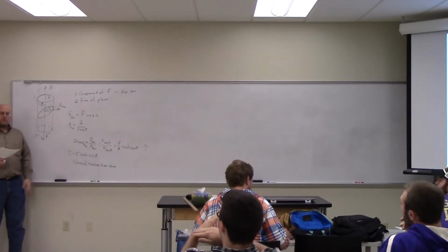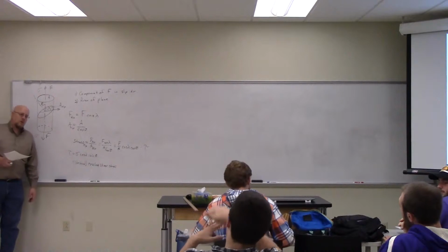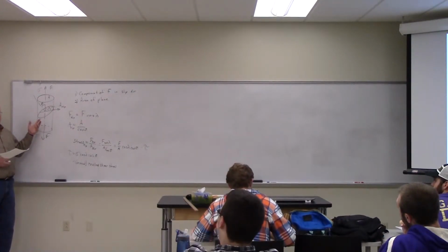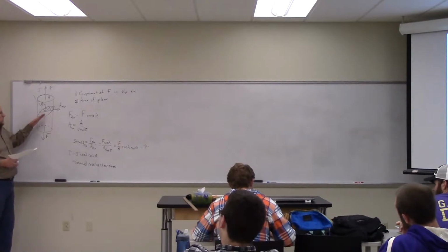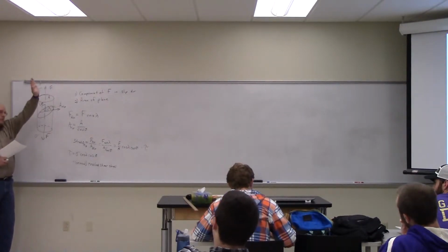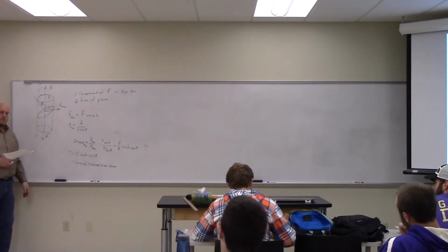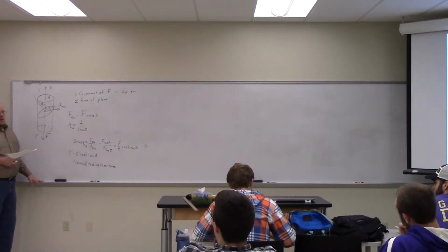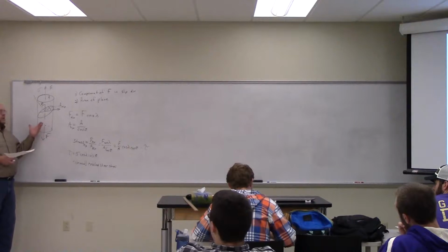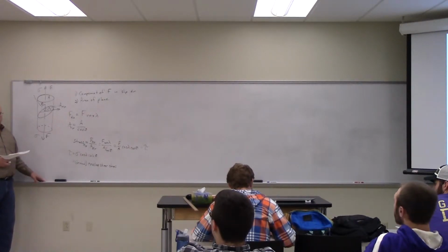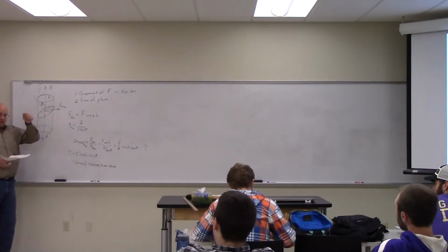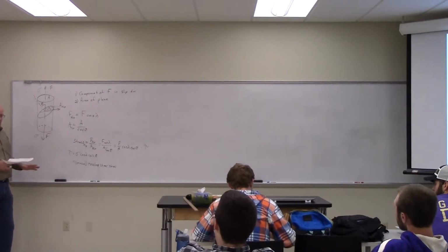So when that breaks, they're going to be like just a slope? So if this were a single crystal, like this, I pulled a single crystal like this, and it yielded, indeed, they would shear past each other, and I'd end up with 2 pieces with a slice on. In real materials, we don't do a lot of testing like this. So this may happen on a microscopic scale, but the next crystal might be oriented differently. So we'll not worry about that right now.